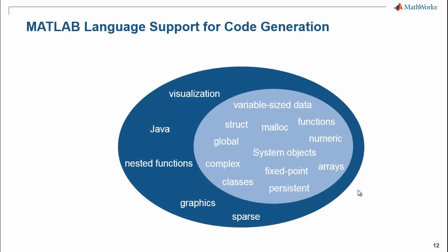Breezing through this a little bit, if you look at the MATLAB language support, not everything in MATLAB makes sense for generating C code. And remember, our goal is to focus on the numerical computation portion of your complete MATLAB algorithm. So a subset of the MATLAB language is supported for code generation. The support is actually quite wide, as you can see here. In any case, this is the subset that makes the most sense in converting to C code.